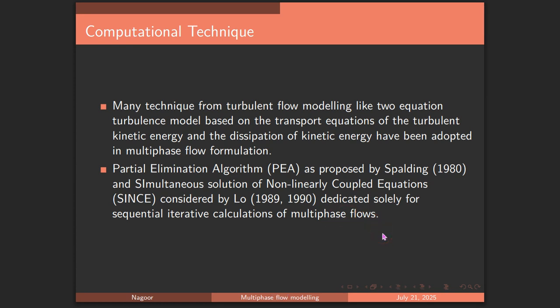However, there are some techniques which existed in single phase flow, like turbulence modeling, the k-epsilon turbulence model, k-omega turbulence models. The two-equation models are similar kinds of logical techniques also being utilized here to formulate multi-phase flow modeling and try to make some closer models for multi-phase flows.